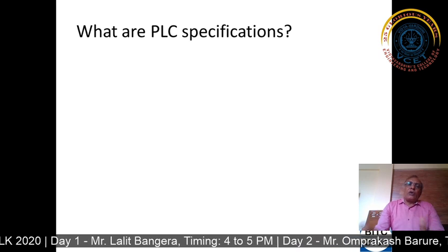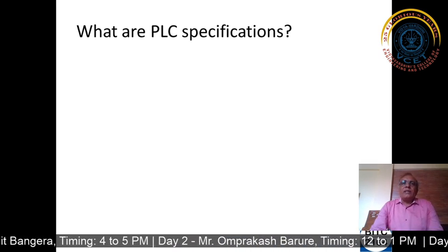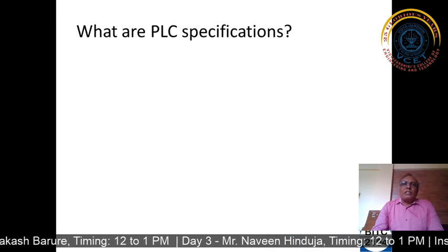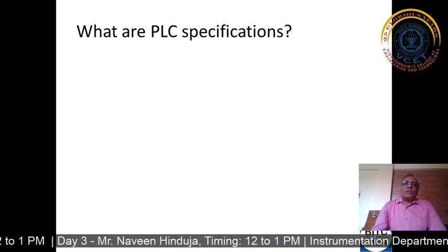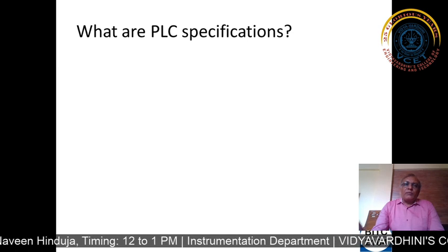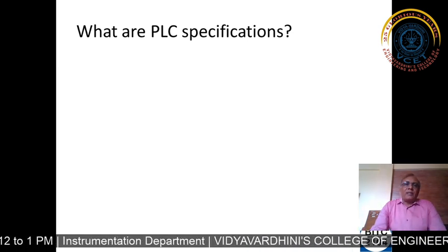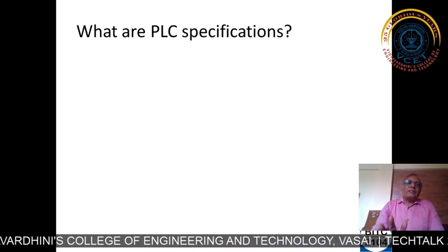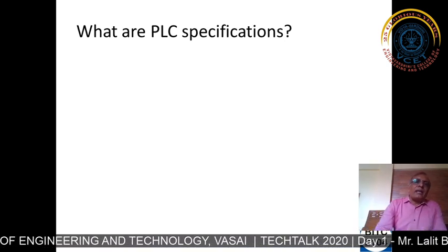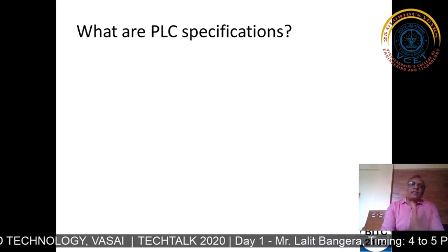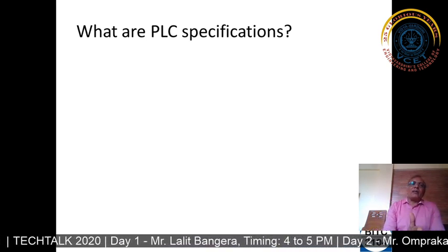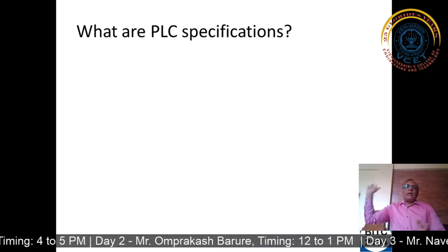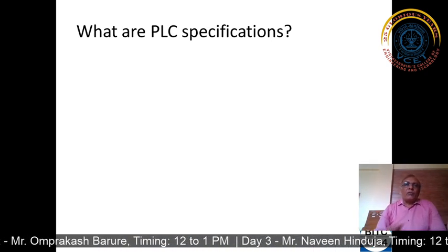Yes. So this is all converted into a standard language. You ask for a beta ratio, and you will come to know about the dimensions of the bore. You talk about the shape of the bore, and you will come to know about the type of the orifice plate. An orifice plate is a very, very important device. I'm not saying that this will go away, because this works with mechanical systems. Once the orifice plate converts its signal, a DP, into something else, then our systems work. Then it can be up to DCS, PLC, whatever it is.